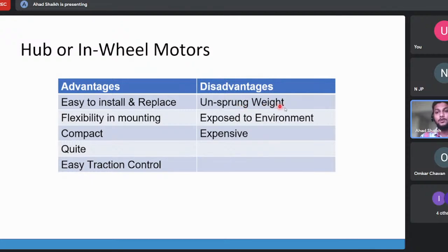They are mounted over the suspension, and whatever comes after the suspension is called unsprung mass. They are directly in contact with the wheels, and whatever loads or jerks are on the wheel will also be faced by those components.